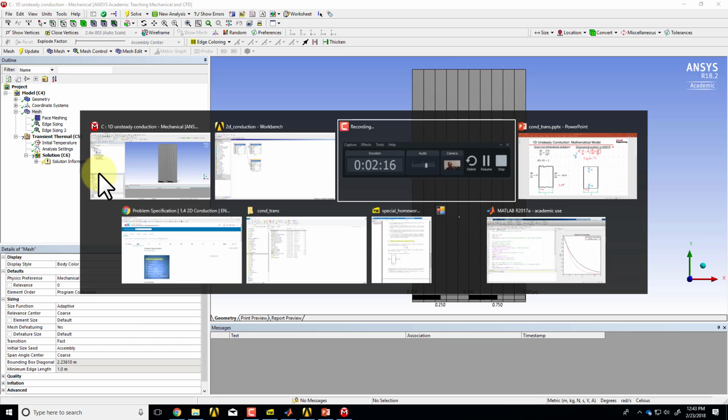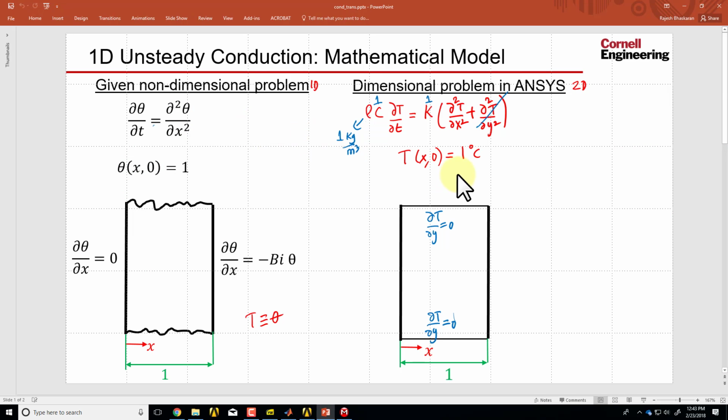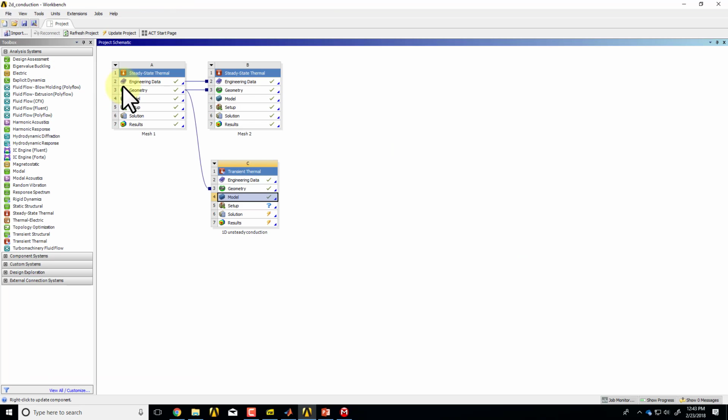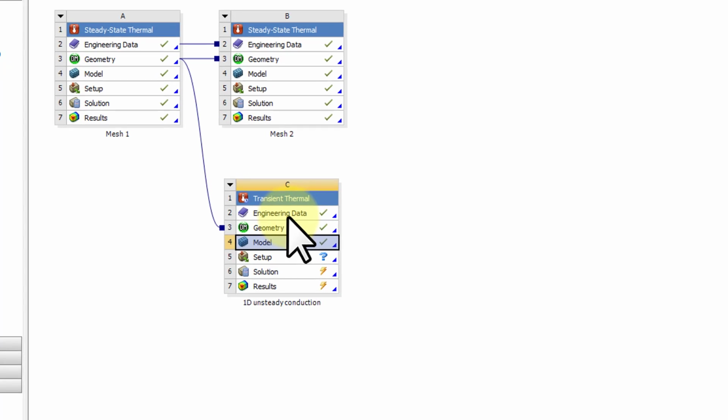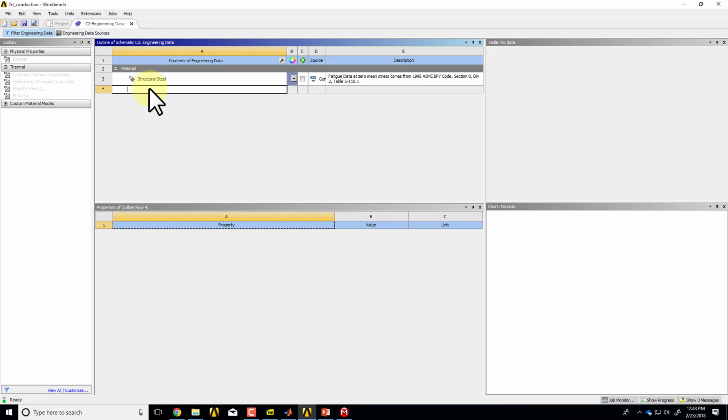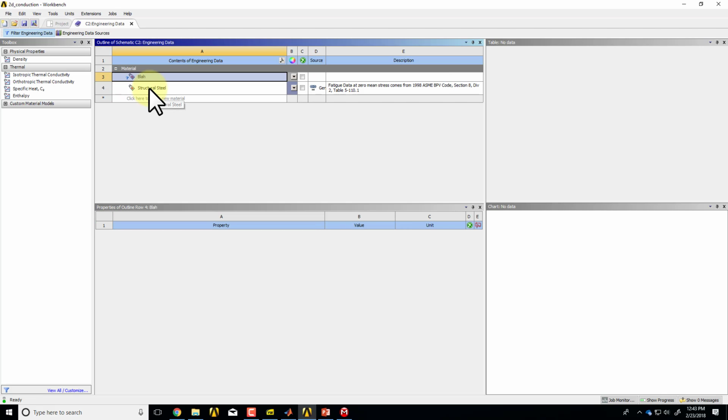And then if I go to complete the mathematical model specification, the mesh, of course, doesn't affect the mathematical model. Let's set the material properties to be 1 so that this equation looks like that. So for that, I need to go to the project page. I will double click on engineering data. I'll create a new material. I can call it whatever. So I'll just call it blah.